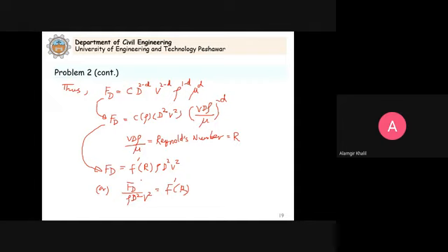And actually, if we go back to what we studied in the Fluid Mechanics 2 chapter, the drag force was equal to CD, the drag coefficient, times rho v square by 2 into area A. You remember this, we studied it in Fluid Mechanics 2, forces on immersed bodies.